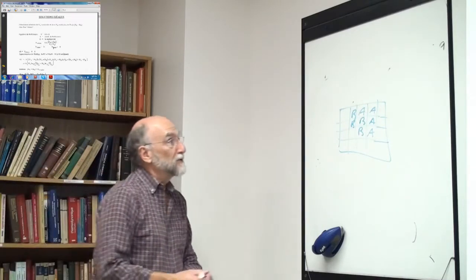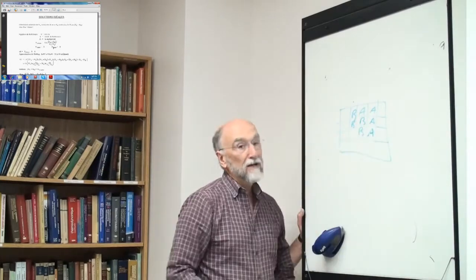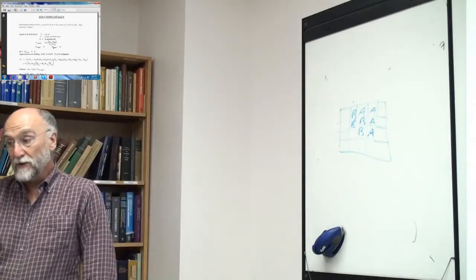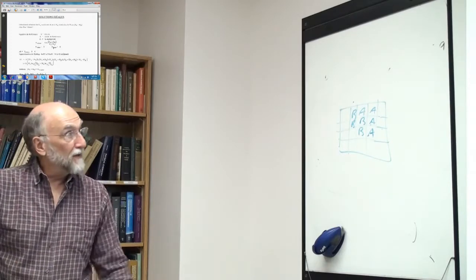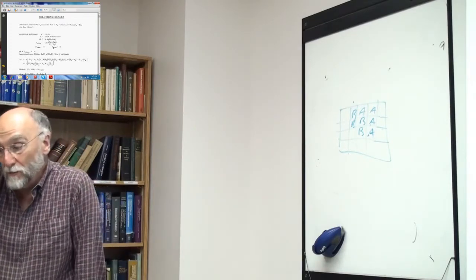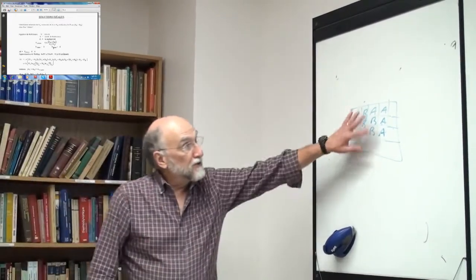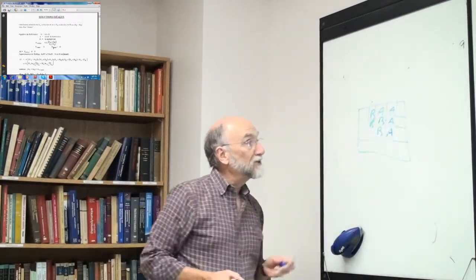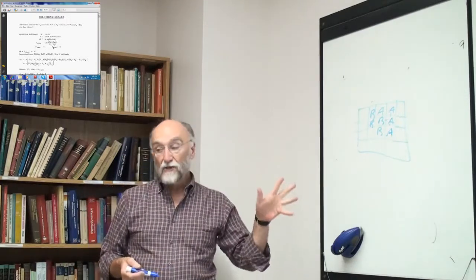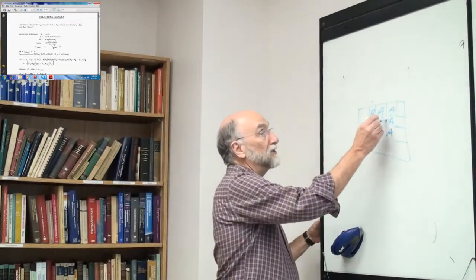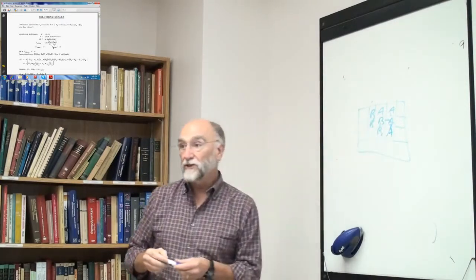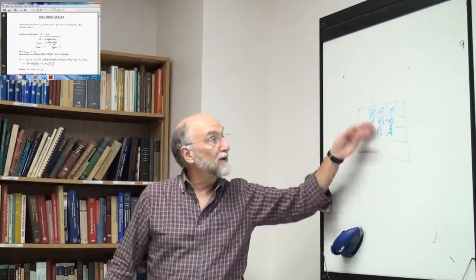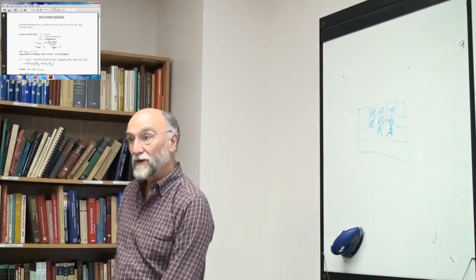The solution is random. That means the probability of an A being here is independent of what's around it, independent of its neighbors. This is because A and B are, we assume, extremely similar chemically. In the limit, the most ideal solution would be a mixture of two isotopes of the same element, but two elements that are very similar chemically are going to be close to ideal. They'll be randomly mixed, for the same reason that they're very similar. This means the enthalpy of mixing is going to be 0. You mix A and B, and the bond energy of an AB bond, an AA bond, and a BB bond all have the same energy. So when you mix them, there's no change in energy. And they're going to be randomly mixed because, again, all the bonds have the same energy, so A and B don't try to get next to anything particular to lower their energy.